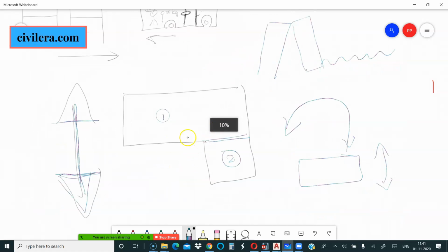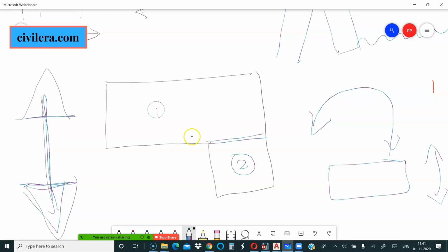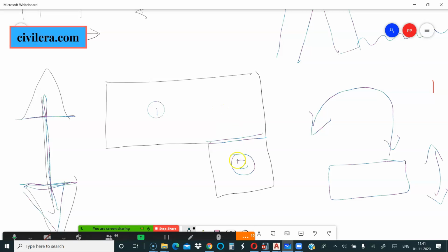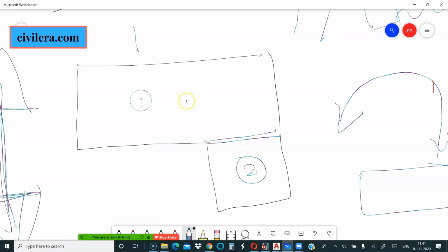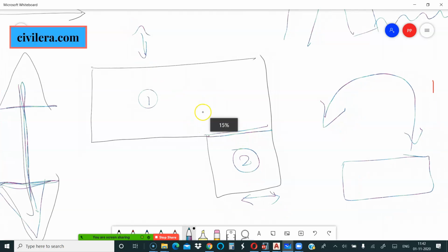But separating this building into two, this is part of your scheme. So if you have a U-shaped building, it may be even 3 buildings structurally. Functionally, it will be a single building with a small gap between them, and people can of course move between them, but structurally you are making it independent. Yeah. So this moves very properly. You will have a linear translational motion as your first mode for both the buildings.